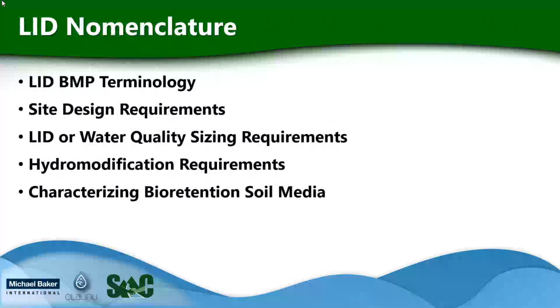For site design requirements, they've focused primarily on the function of LID BMPs on the site before the implementation of structural BMPs, such as conserving natural areas, using permeable materials, and minimizing soil compaction. Regional site design requirements retain the same general focus, but vary significantly in requirement details.